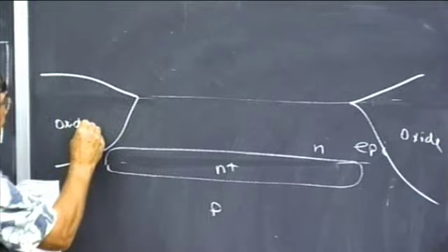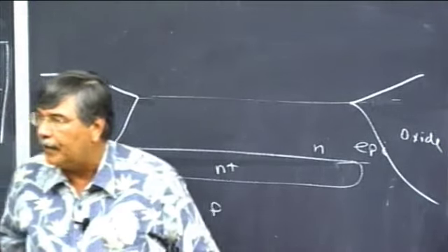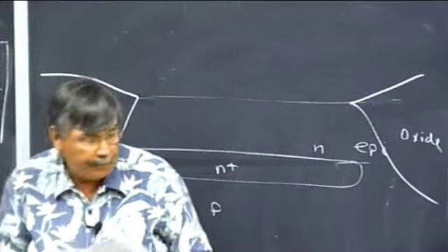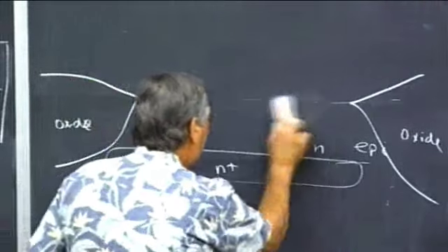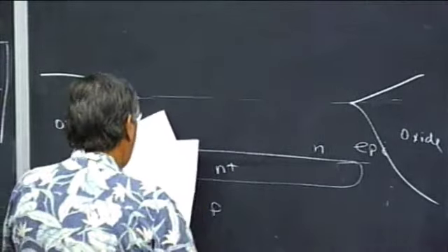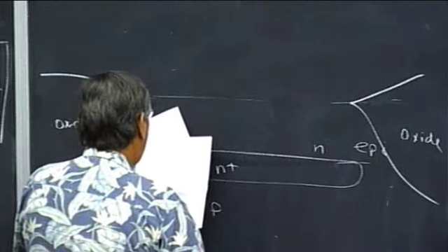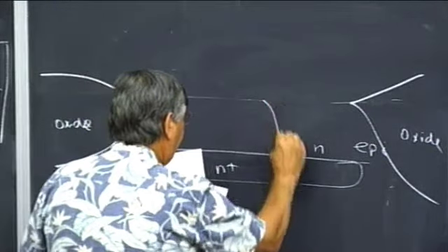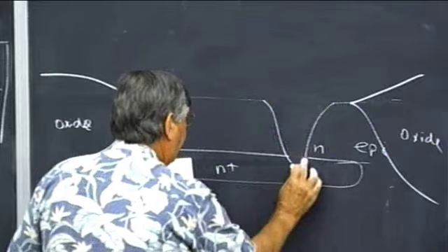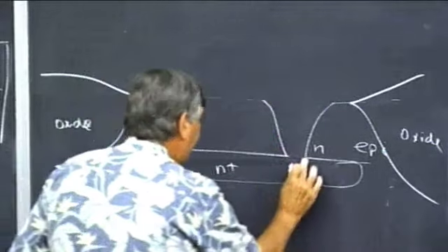All right, so this is silicon dioxide. Silicon dioxide's an insulator, as I assume everybody knew. And I'm going to put in a big chunk of field oxide that goes all the way through the epi. So some more oxide into here. And that's going to isolate this contact over here.